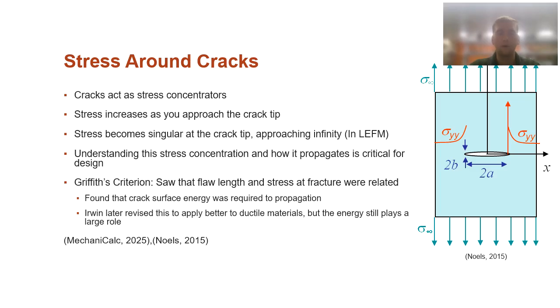Again, Griffith and Irwin do a lot of work in this area, a lot of historic work that comes into play, and they essentially like to relate this flaw length or crack length and the stress at which that fracture will propagate. They were kind of one of the original ones to relate energy to this equation, but we'll see Bazant takes that energy that we're talking about right now and applies it to the size effect a little bit later on.